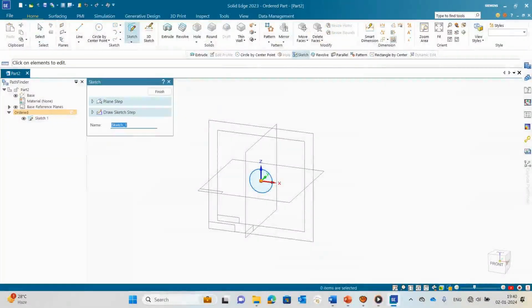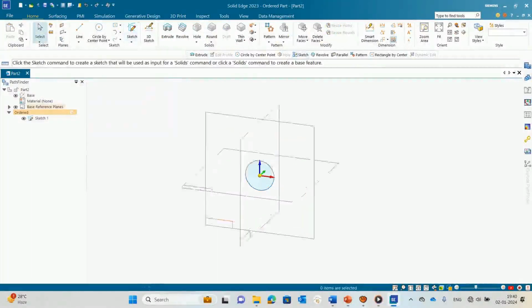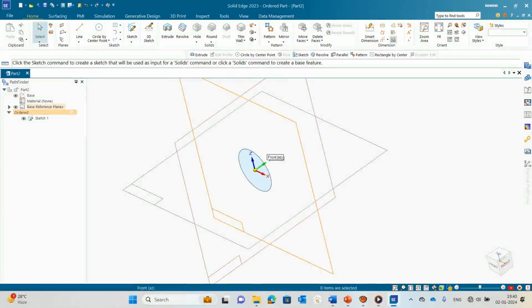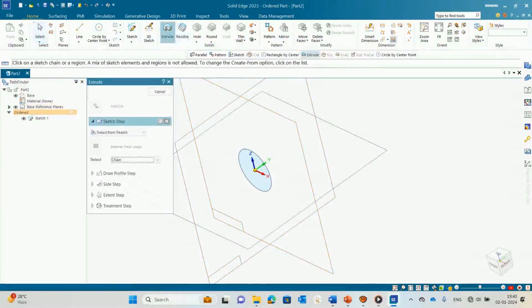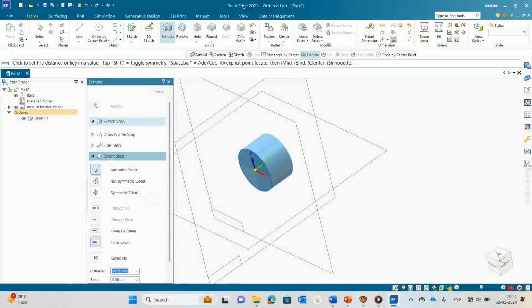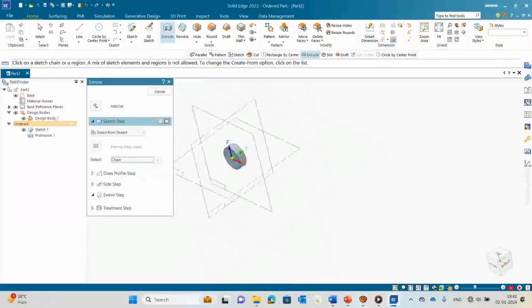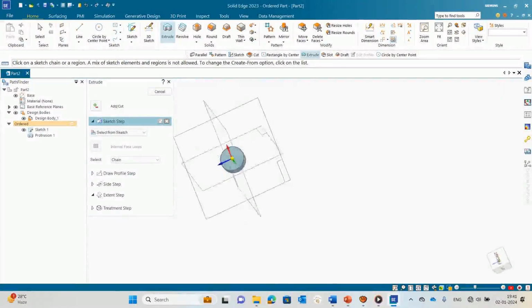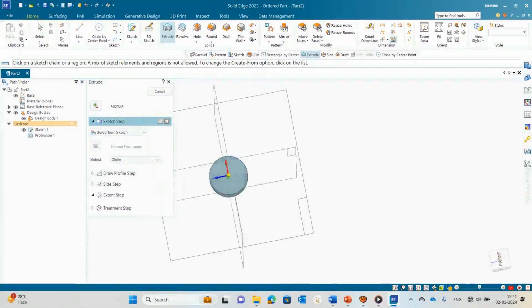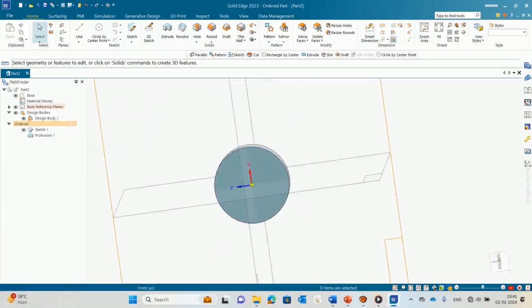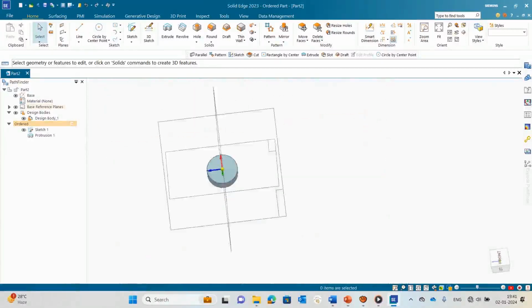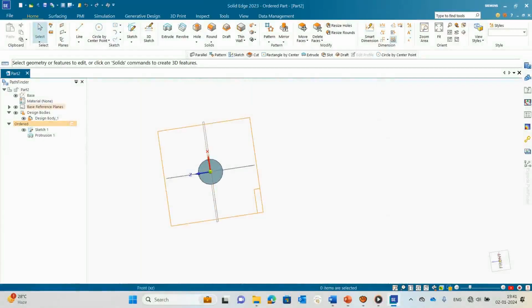Okay, then we will create the swirler vanes. So first, this is the center hub for the swirler. Now I will extrude this one up to 10 mm distance. Okay, fine. So this is the hub. Now we need to create the swirler vanes. Here I am creating the vanes with respect to any one of the planes, x or z. So I will create one parallel plane.